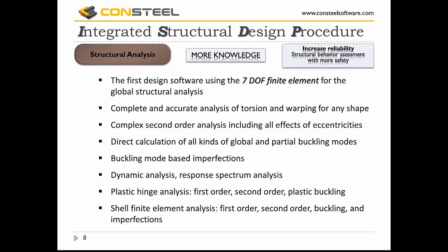We can perform dynamic analysis and response spectrum analysis using this special finite element. We can do plastic hinge analysis, first, second order, or plastic buckling as well, including not only the in-plane second order effect and buckling, but out of plane effects and buckling effects as well.